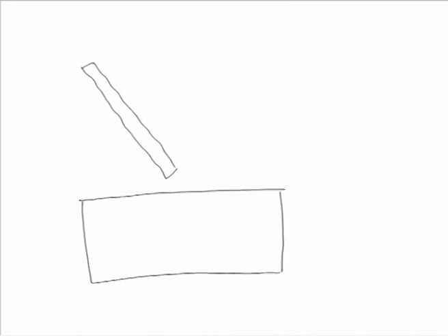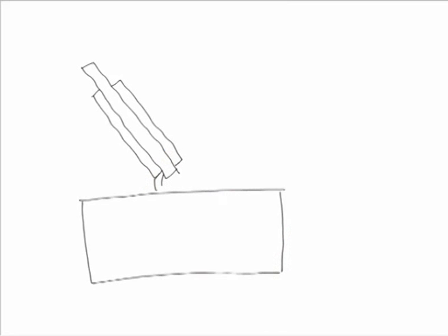To understand this, if we see this diagram here, say this is the base material and this is the electrode core wire with the coating material all around it, and the current flows through the core wire to the base metal and an arc is developed.